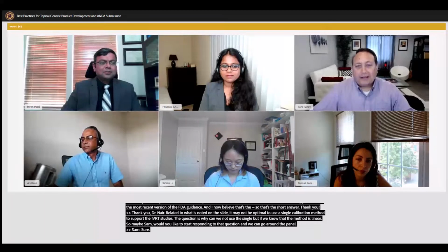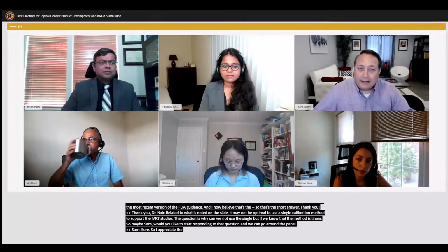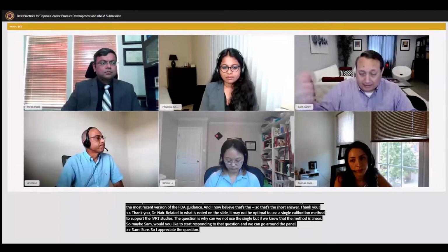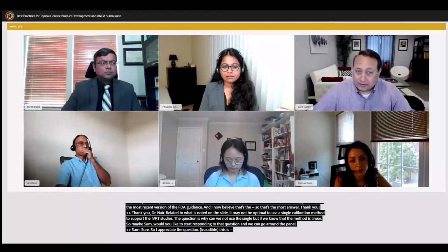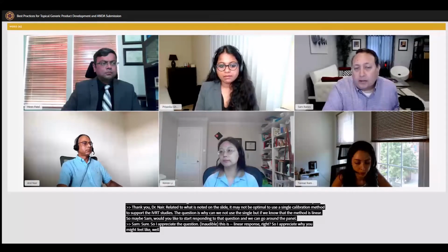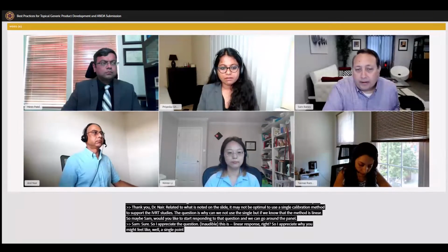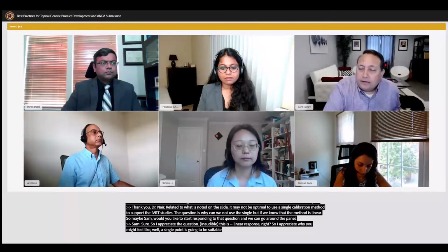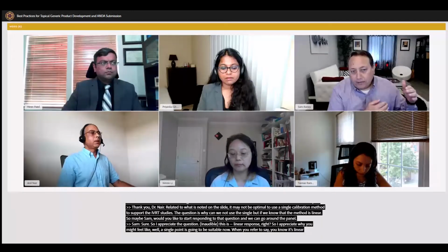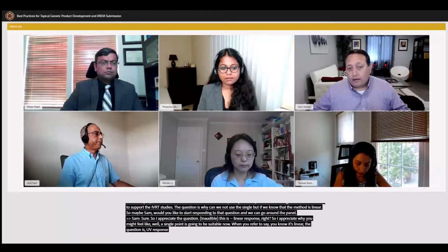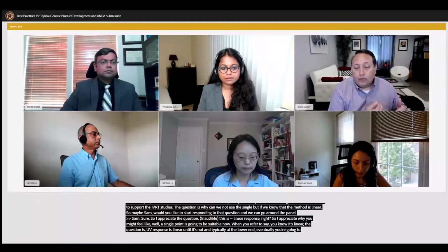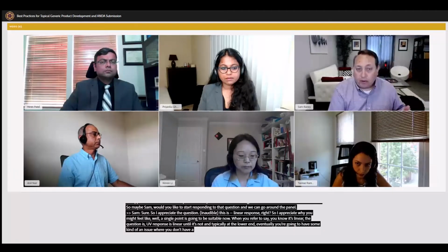So I appreciate the question. LCUV, diode detectors, it's traditionally very linear response, right? So I appreciate why you might feel like, well, a single point is going to be suitable. Now, when you're referring to saying that if you know that it's linear, the question is, UV response is linear until it's not. And typically at the lower end, eventually you're going to have some kind of an issue where you don't have a linear and proportional response.